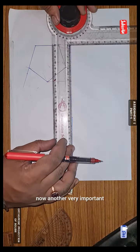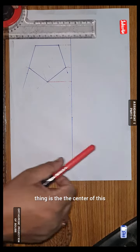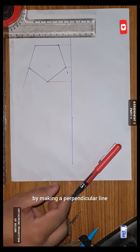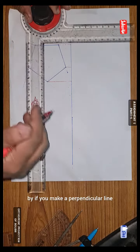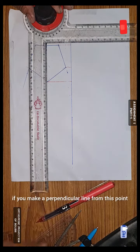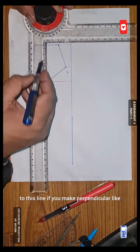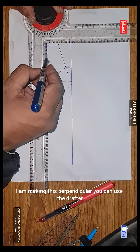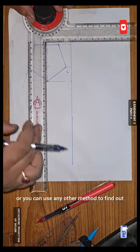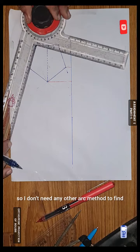Okay, now another very important thing is the center of this pentagon. The center can be found by making perpendicular lines. If you make a perpendicular from this point to this line, you can use the drafter or any other method to find the perpendicular. I am using the drafter, so I don't need any arc method.